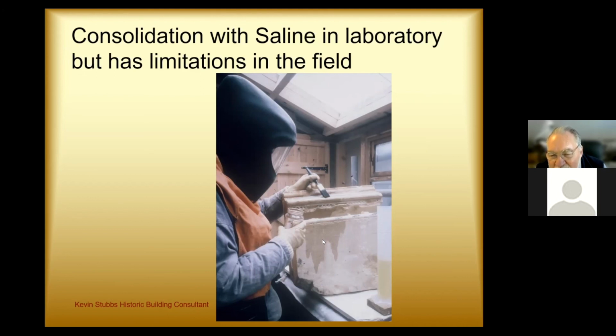The stone has to be absolutely dry. Well, in this country, when do you get more than a few days of drying sun and winds on all surfaces of our historic buildings? So it works fine in the laboratory, but not in the field.